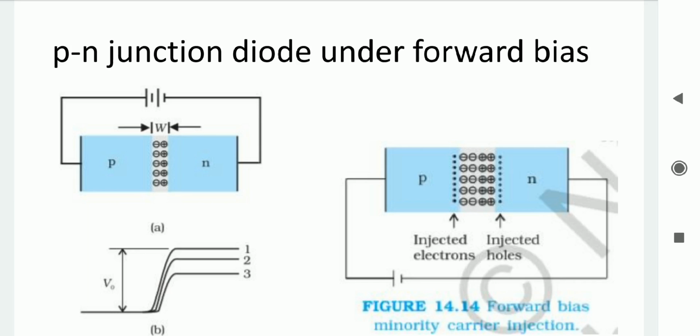These carriers can cross the junction and generate a small current in microamperes. If we increase the applied voltage beyond the barrier potential, then more carriers can be energized and the current increases. After the built-in potential, the given supply will generate current in milliamperes.